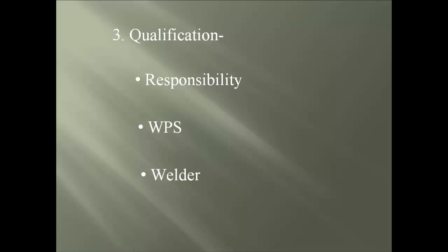in one of the following positions: the flat, rotated at a 45-degree angle, the horizontal, fixed, or the horizontal rotated, the overhead fixed, and lastly, the 5F position, which covers multiple welding fixed. The welder certification uses the same destructive tests as the WPS, which are the tension and macro etch, but for the fillet weld, it uses a bend test of greater than 30-degree angle.